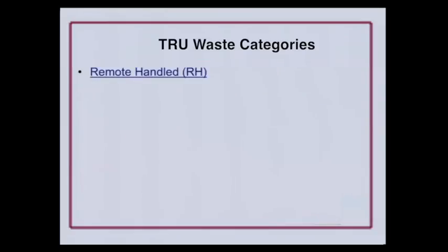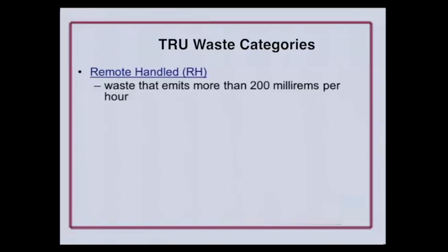Now, the other category is remote handling. That's just what the name implies. It has to be handled remotely. And the reason is the dose rates, greater than 200 millirem per hour on contact. It does require special equipment to handle it. If it's remotely handled, it doesn't make sense that you can do it with just normal equipment.